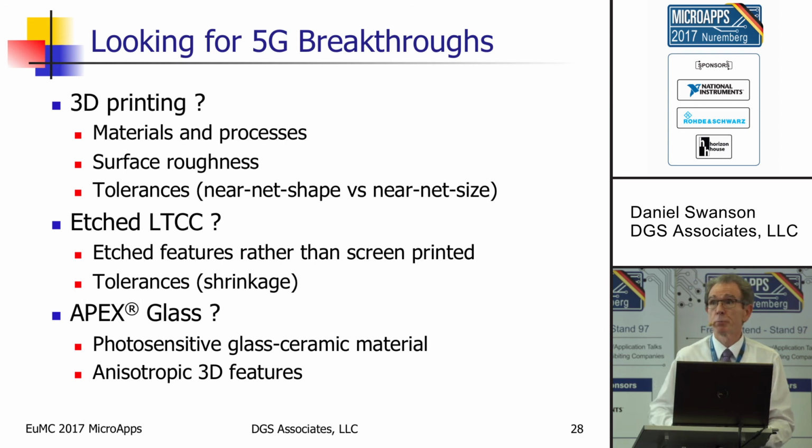And I've seen some pretty good results at KU band on an LTCC filter. Depending on exactly how they do this, you've still got some shrinkage issues with LTCC.